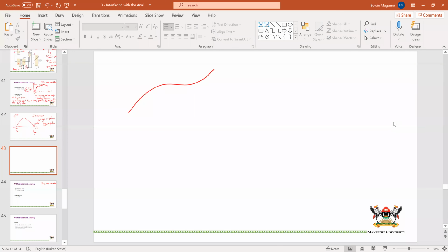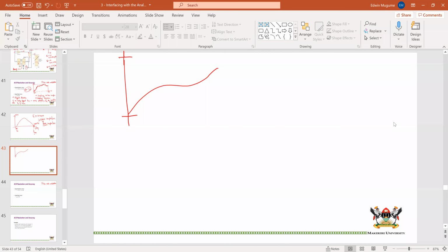Now let's say that we have a signal like this. We know the rate, we know this speed and that. We know the maximum amplitude and the minimum amplitude, all right? And we have taken our samples at a rate that is in line with the Nyquist theorem, so at least twice the signal frequency. If we sample at least twice, then we will be able to reconstruct the signal and intelligibly decode it. If we do not, we are going to have a problem, and we're going to see what it means.